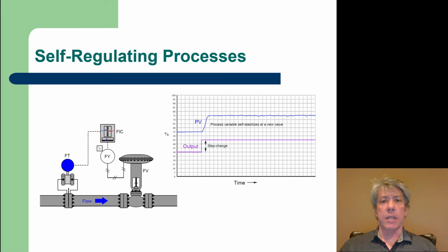As I said, FIC is the flow indicating controller, and it's just a control device. This is where we'd set our proportional and integral derivative gains if we intend to use all of those. And here we could read off the current setting. In other words, where we want the flow to be and where the current flow rate is actually located, the process variable.